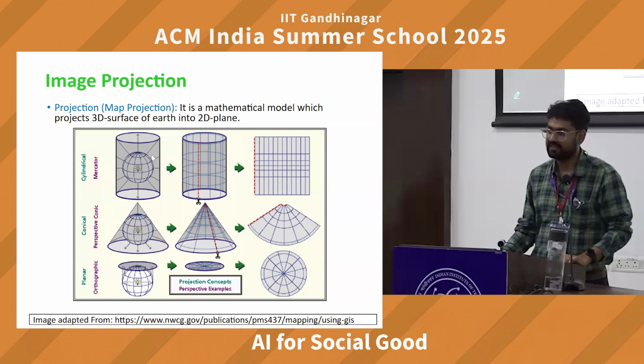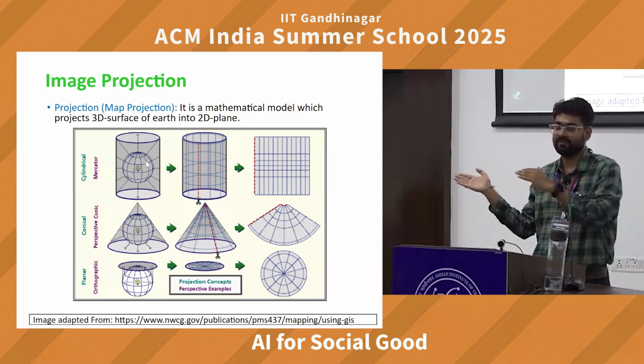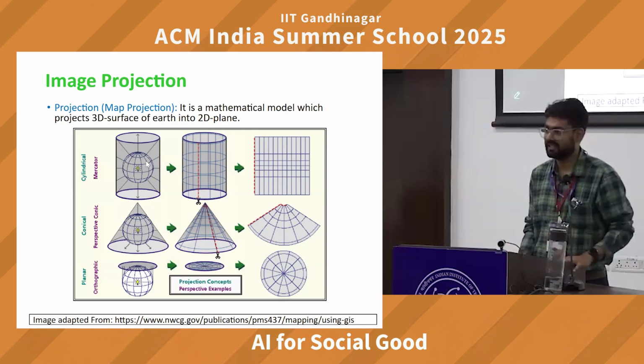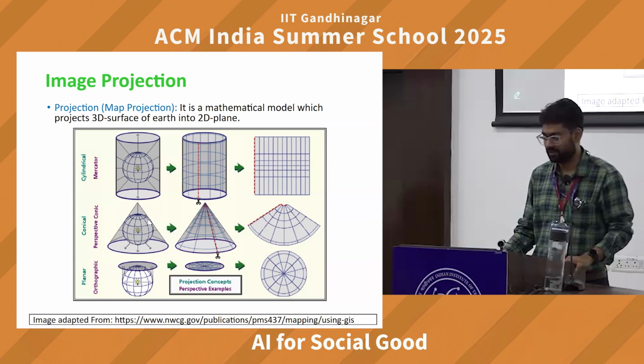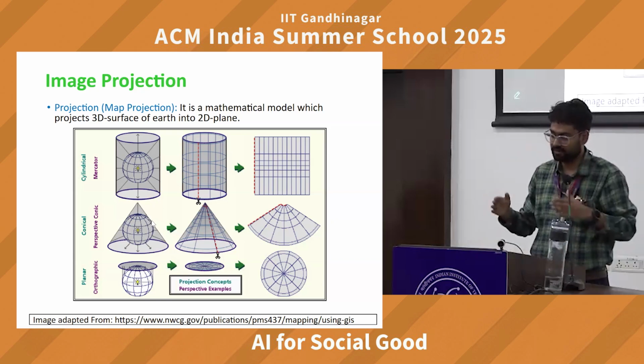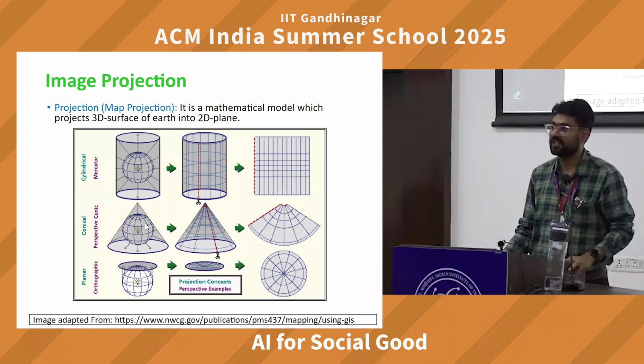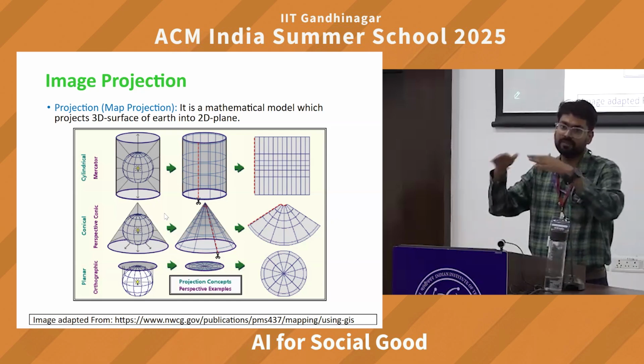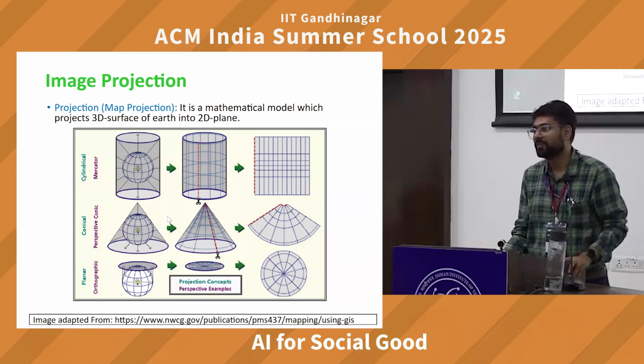Here in this case, the distance between latitudes is increasing when you are going from the equator to the polar side. Similarly, another projection surface can be a cone. Such projections are called conical projections, and are typically useful for the mid latitude. In a conical projection, the two sides of the cone pass very closely to the Earth's surface, where the error is minimal. It typically happens very close to the mid latitude, and that is why it is suitable for mid latitude areas.